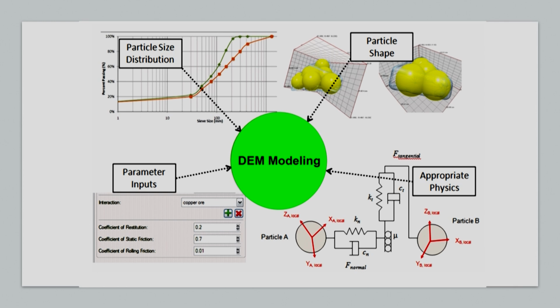If it is a sphere, it is very easy to do. If it is an oval shape, the shapes are formed by clubbing different spheres. We can also define the particle size distribution. Say my particle size varies between 9.5 mm and 10.5 mm. We can define that while feeding also.